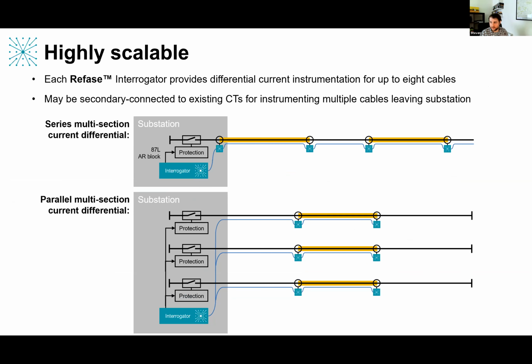And it's classically very difficult to do with distance protection, especially if you've got multiple cable sections dotted in between your overhead line sections, because there are non-linearities involved. It's plausible, but it's very hard to give you 100% confirmation of where the fault is located.